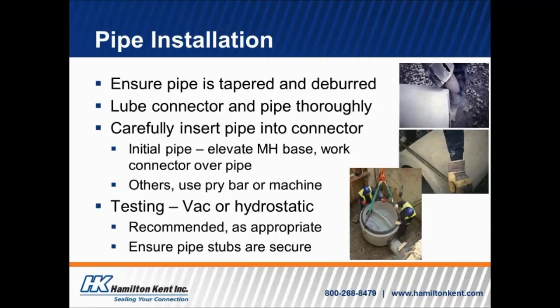And then for testing, you can use either vacuum testing or hydrostatic testing. If you're able to block off that line and do testing, that is highly recommended. You need to make sure that you have pipe stubs that are secured inside any types of openings that don't have the pipeline included in it.